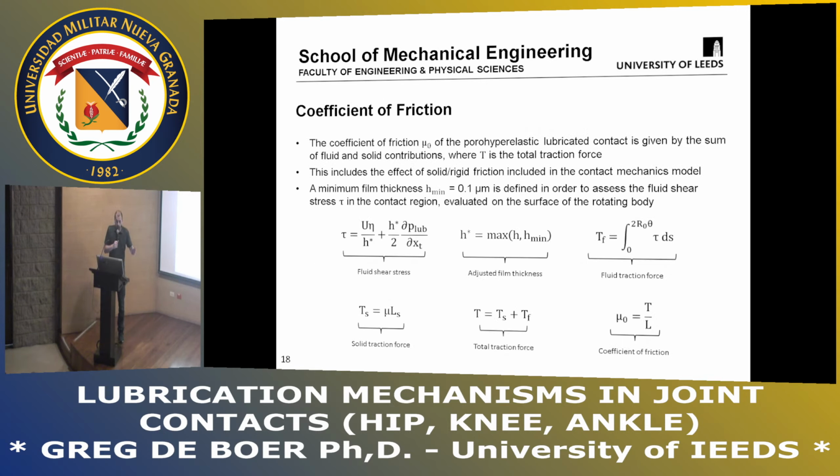Great. And then we can also measure friction. So it's tribology, we're always interested in friction, and these equations allow us to do that. Once we've solved the problem, and we have our pressure field and our displacement field, we can then post-process that data and calculate the traction forces. So these are the tangential forces in the contacts,